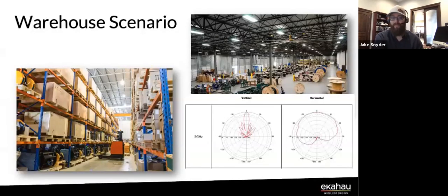The thing to remember is trying to put RF where you want it. The higher the gain those antennas are, the more narrow their vertical beam width is. So the Wi-Fi was terrific 40 feet in the air, but it wasn't so great down below because the gain down below the antenna was actually fairly low.